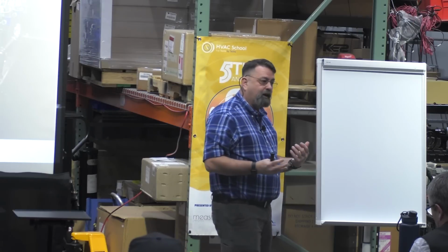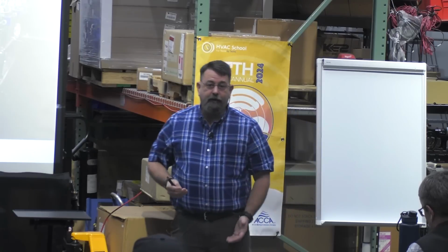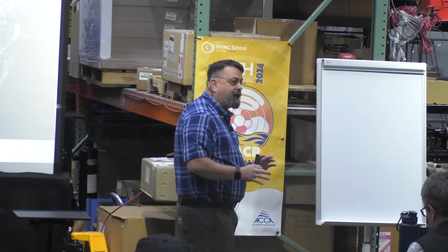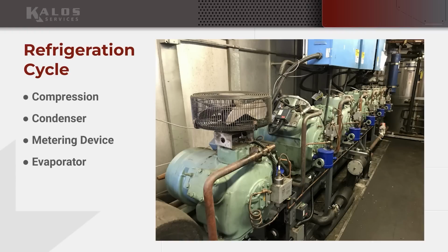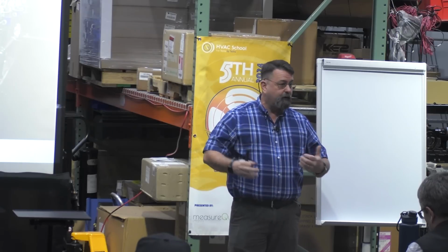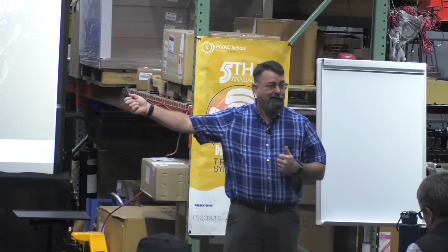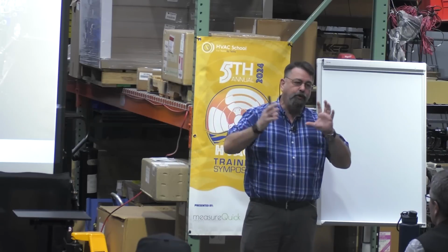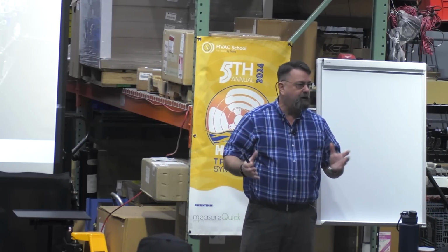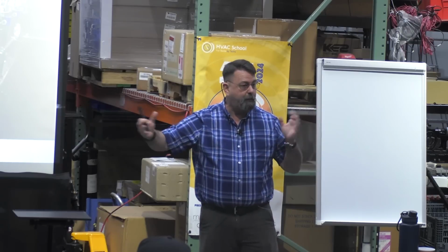Well, residential guys are seeing variable capacity, right? Two-stage compressors or compressors that ramp up and down with VFDs, or you're doing that now. Well, so are we. We're just doing it old school by having different size compressors and different amounts of compressors running. If I need a bigger compressor, I just turn on another compressor. If I need a smaller compressor, I just turn one of them off, right? And the whole unit acts as one compressor. So I can make it very small or very large based on my load.